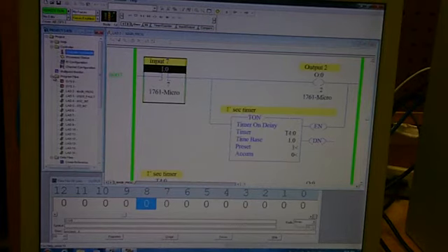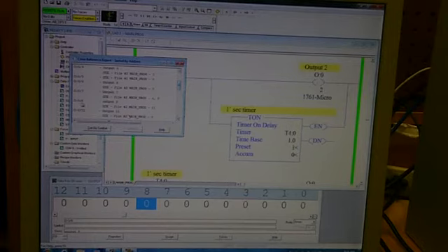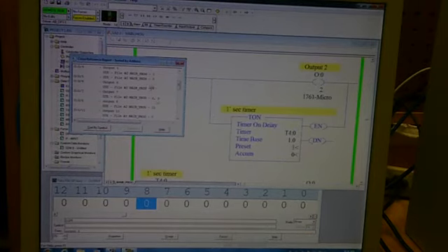Because something's linked between them. The rule says that for my output, it can only be in one run. I have output 7 in 2 runs, in run 4 and 9. The program is a sequential program. When it gets down to run 4 and turns on output 7, okay, that's fine.